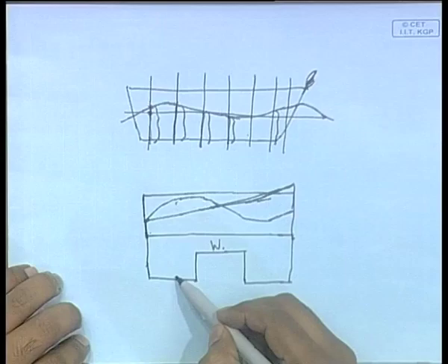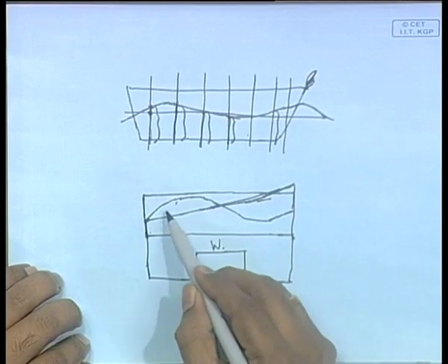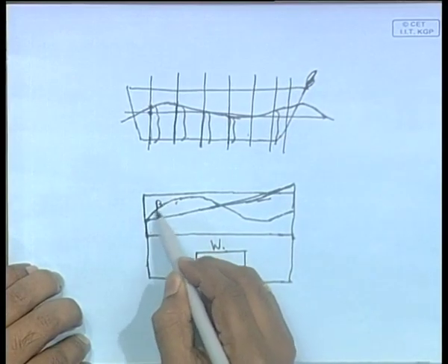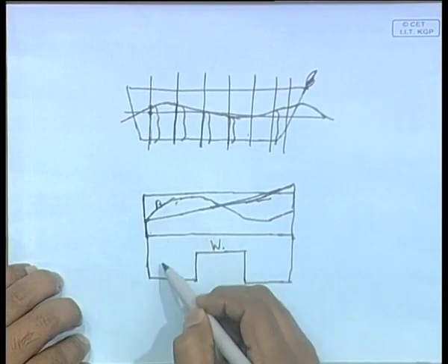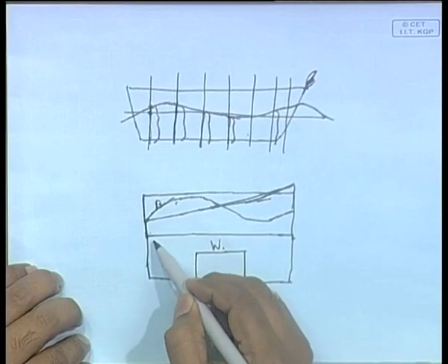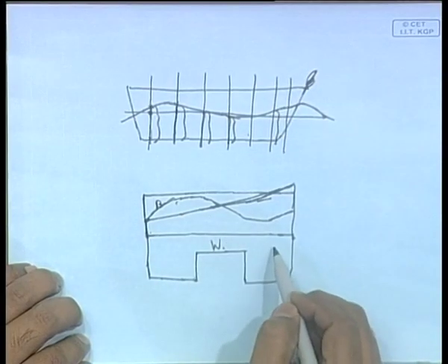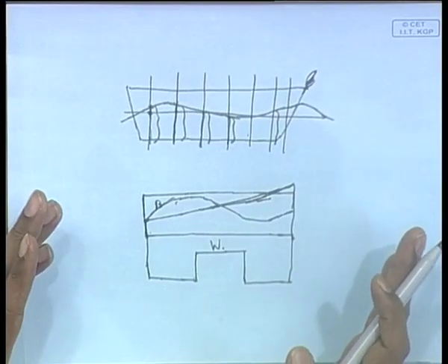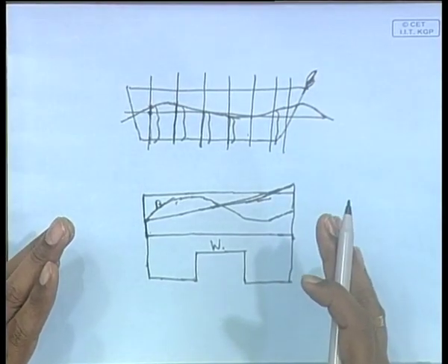So, when the buoyancy curve varies, consequently the weight minus buoyancy curve will also vary. Weight is fixed, we have that curve. So, this weight minus buoyancy curve will have a particular fashion of its own. If this is the weight curve and this is your buoyancy curve, then the weight minus buoyancy, another curve will come as a function of distance, that gives you your load curve, and that curve you now need to